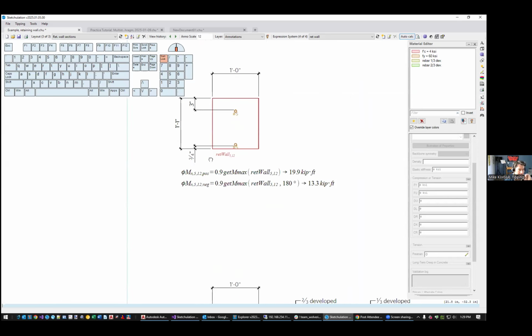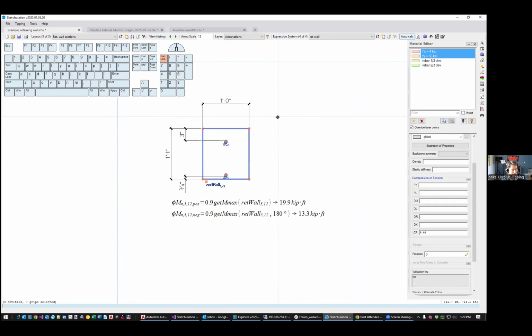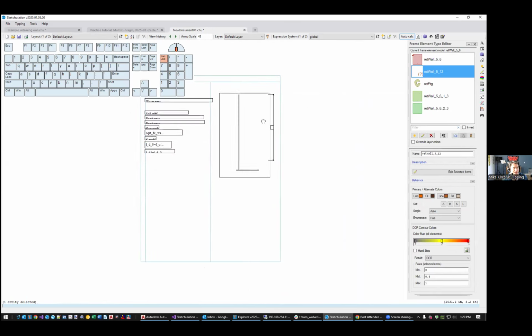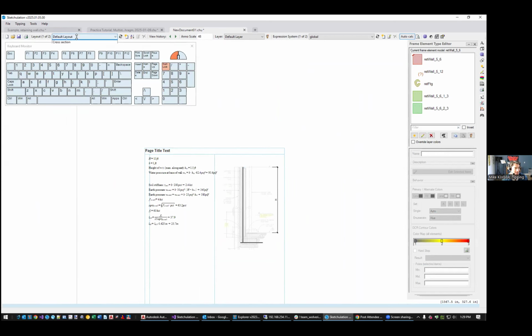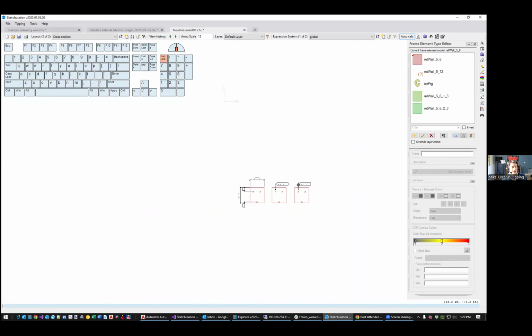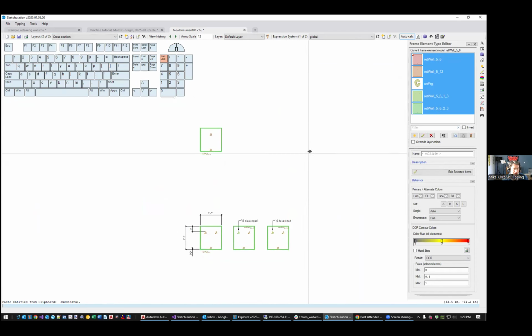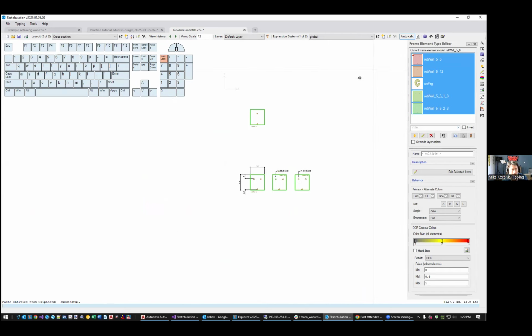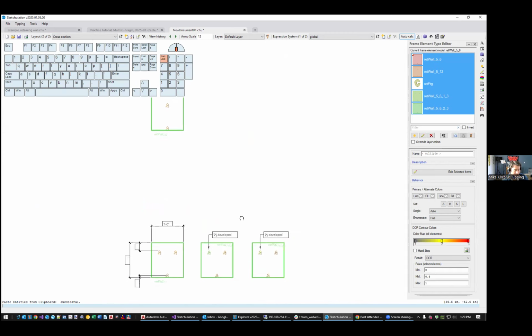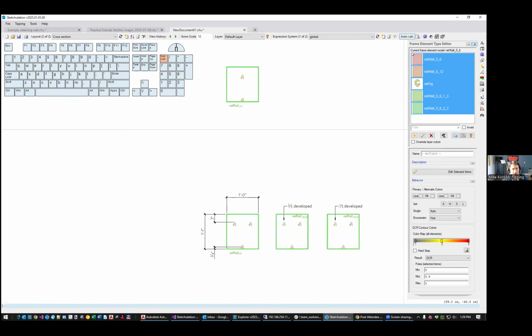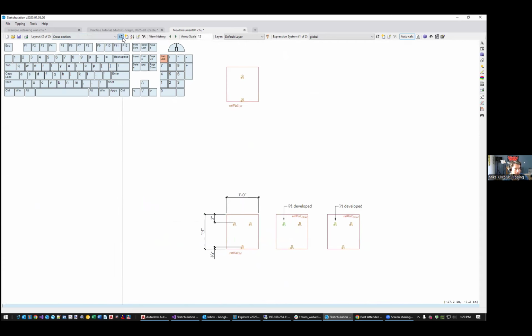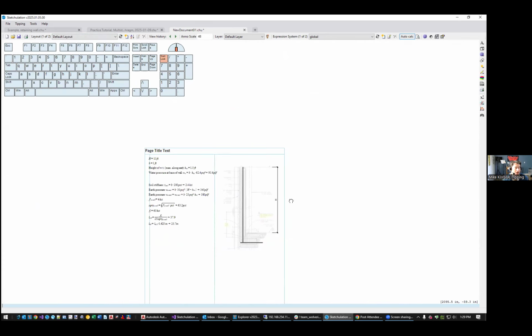So I go into this. This is my standard 5s at 12 cross section. I'll copy that and then paste this over to my cross sections layout, and now my 5s at 12 frame element type is all defined. So copying and pasting is usually pretty good at bringing everything over, all the dependencies, so that you don't have to redefine something in the new document.